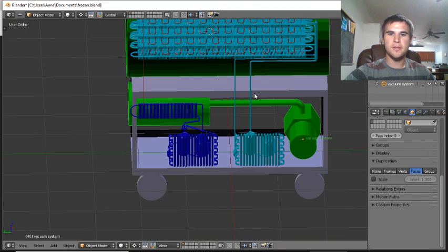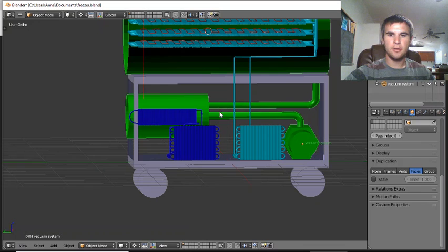If you put ball valves here and here that were refrigerant or vacuum tight, you could, in the middle of a session, if you were doing something like soup that had a huge amount of moisture and you completely plugged up your evaporator with frost to the point where it wasn't effectively working anymore, install vacuum tight valves here and here, and then isolate the product chamber. Actually, you'd only need to isolate the product chamber. The pump could be fine. So you isolate the product chamber, break the vacuum in the cold trap, melt the ice, drain the cold trap, and then start the vacuum again.